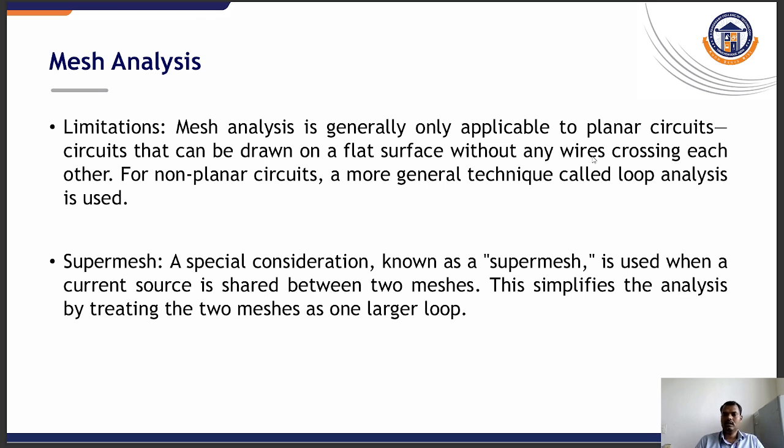The limitation is that it is only applicable for planar circuits. When wires are crossing, the mesh analysis is a little bit difficult. In those cases, they are known as non-planar circuits, and we can go for loop analysis in order to find it out. And the next, super mesh.